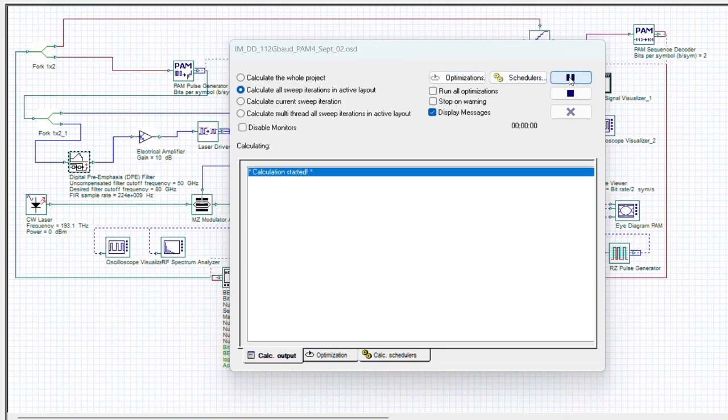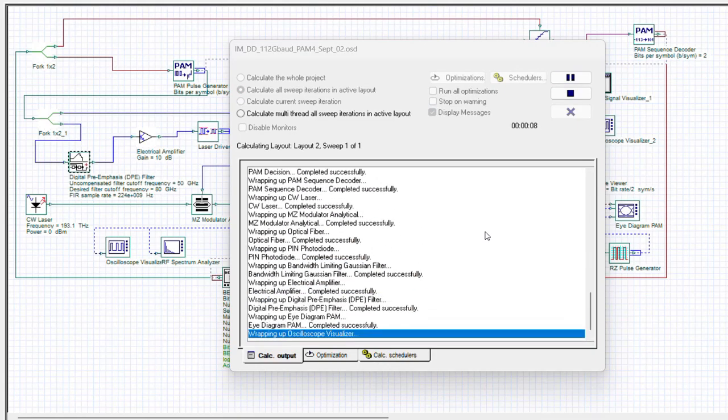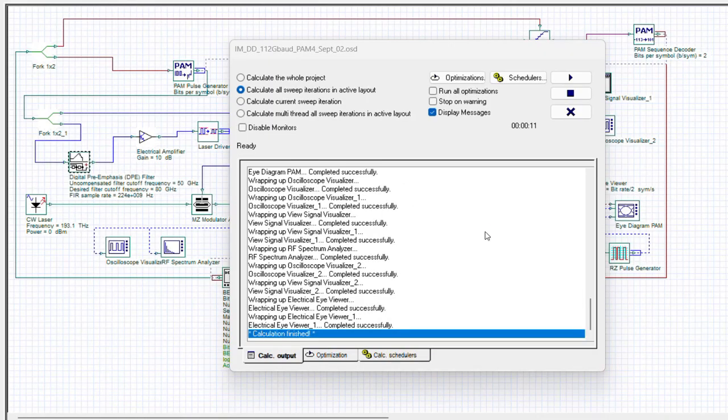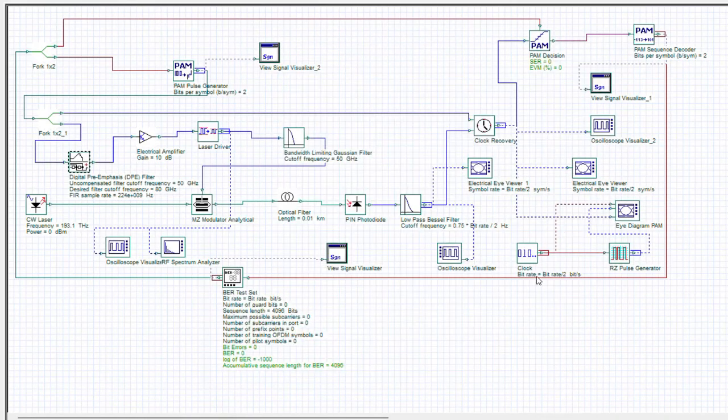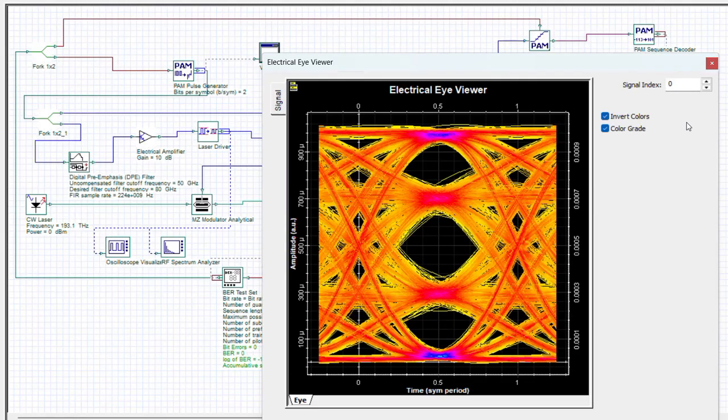And if we run this model here, we'll start now seeing a more reasonable and expected response, where the speed of the digital analog converter that will be implemented after the FIR filter coefficient and within the hardware limitations actually is consistent and reasonable. You can still see here we have error-free operation, and observing the eye diagram, it's fairly open.